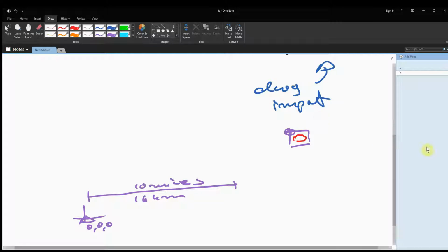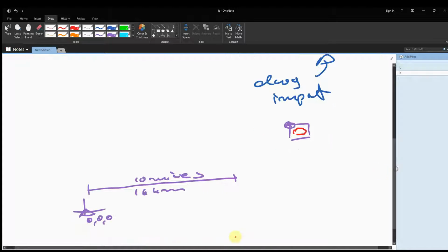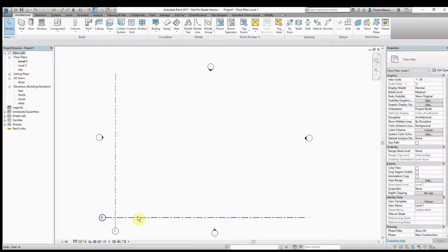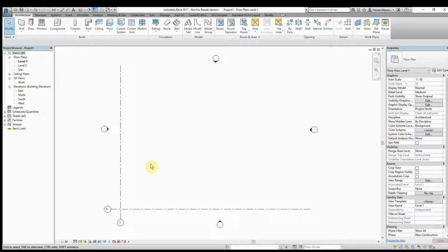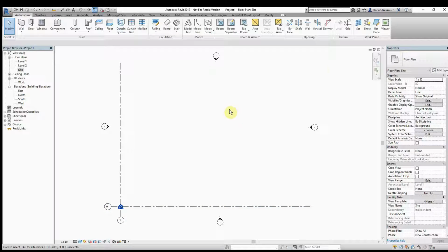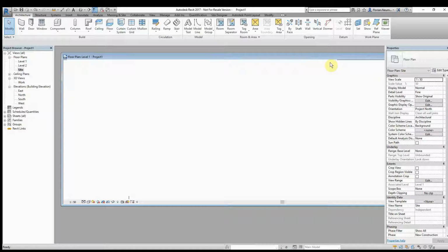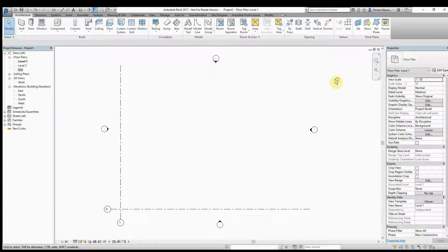So to practice this a little bit, we first switch to Revit here. I have a Revit open, and for many the first big question is, where is the survey base point, what is my project base point, and why and how do they work with each other. We find here with the standard default architecture template something called site. And here on the side, these two can show up. When we go, for instance, here, let's just close this and make this a little bit larger here. Come on, be nice to me today.